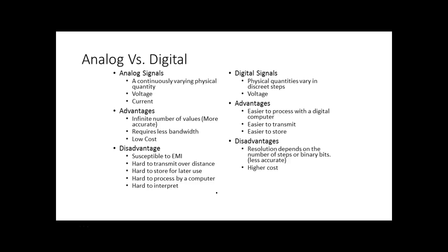Because if I generate a current, if I generate a voltage, I've got to cause something to move. If I have a current, I've got a resistance. If I've got a wire I'm sending that through, every wire has resistance. If I send a current through a wire, we have a voltage drop. We have ground differentials. We think of ground as 0 volts, but it's 0 volts where you're at, right? You understand? So if I've got a building that's 1,000 feet long and I've only got one ground in my building, I guarantee you could go to the electrical outlets on one side of your building, and if you could stretch your meter long enough over to the other side of the building, there would be a difference in potential between the two grounds. So a 0 volt potential is almost impossible to maintain over distance.